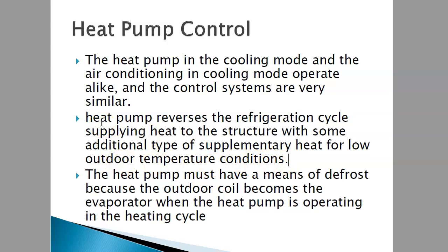So basically, when a heat pump functions, it is reversed, because currently, as you know, the evaporator is inside the room and the condenser is outside the room. If you want to heat the room, the condenser should be inside the room and the evaporator outside the room.